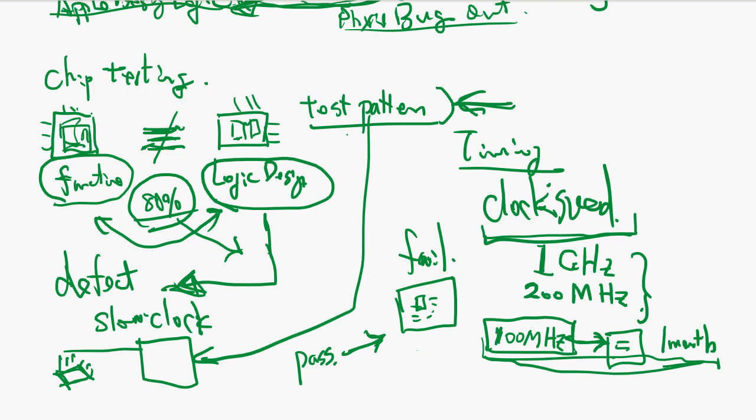With FPGA chips, it's very difficult to predict what the clock speed will be in the end. EDA tools kind of tell you what it's going to be, but when you run it after programming, cutting a fuse and so on, there's a lot of unused metal hanging around, and the gate delay time is not guaranteed, and it becomes very slow. FPGAs tend to have a very slow clock, and even then,